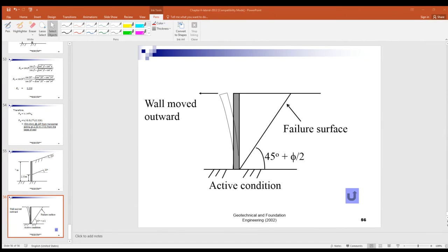And the building is very thin, the wall is also very thin, so they may not resist the bending moment. So the structure may be broken into pieces due to the horizontal force and the great horizontal moment.